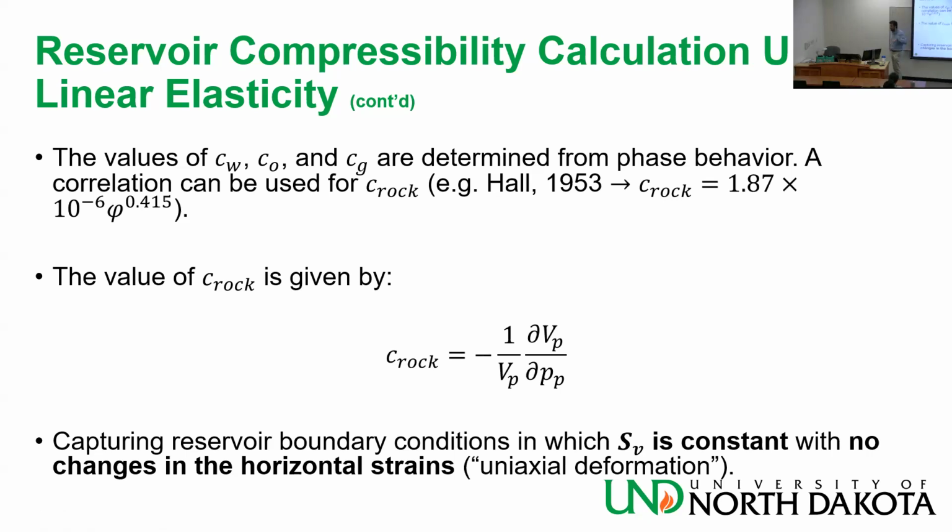In this class, we focus on the rock mechanics, like stress and deformation. Those boundary conditions are what we talked about in module one, like SV, SH max, SH min. Compressibility goes both ways, so it affects both. Reservoir and geomechanics people are interested in that.